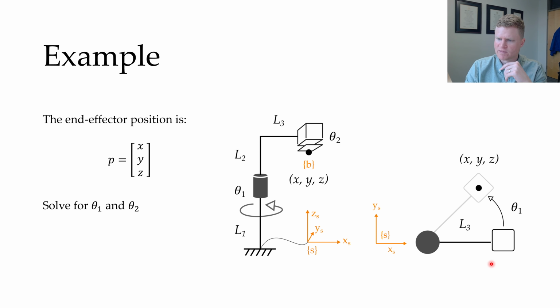And then here's a top view of that same robot. So we're looking down at the robot. Here's this revolute joint right here. Here's the prismatic joint from above right here. And then here you can kind of see how this whole thing rotates as I turn that revolute joint. So if I want to reach some very specific XYZ position, for example, I want to stab that strawberry, and it's right over here, and I know where the strawberry is. So if I give you a target XYZ position, you need to figure out what values of theta 1 and theta 2 are going to be able to reach that XYZ position. And that's a problem in inverse kinematics. Maybe you want to take a second, pause the video, and see if you can solve the inverse kinematics problem for this simple robot arm.